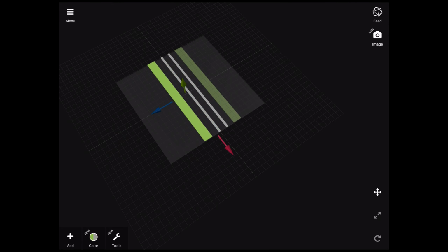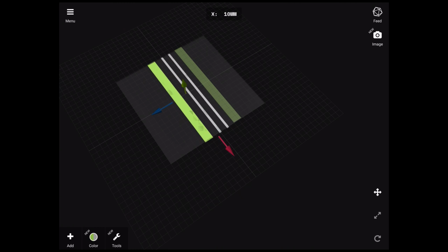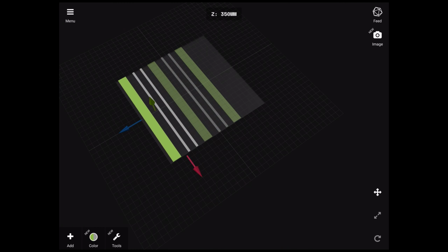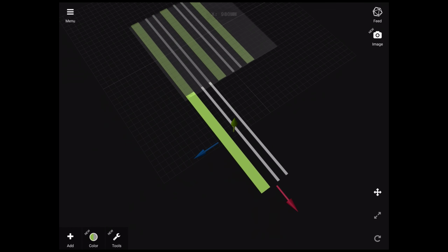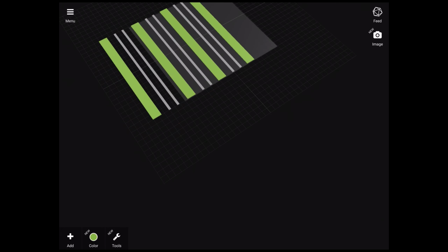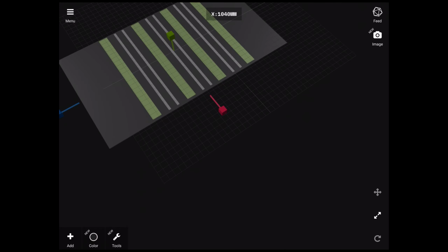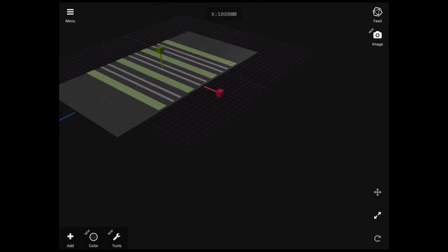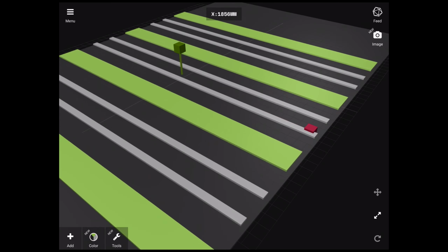So you'll see here that I'll select 3 objects and then clone them, and then I'm going to move them. I've got snap to grid on, and I just move all of it. So I'm just doing it by eye. It's not super accurate here. Let me do that another time. And there I've got an array. So it's much quicker to create a sort of tessellating pattern or array of things than doing everything individually. Less errors as well. So I was just extending, scaling my tarmac underneath to suit.